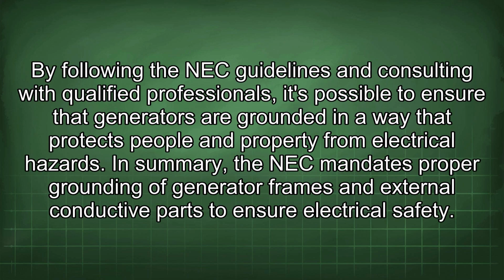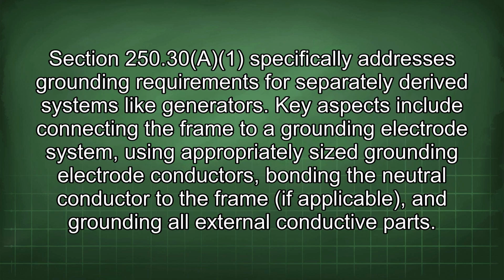By following the NEC guidelines and consulting with qualified professionals, it's possible to ensure the generators are grounded in a way that protects people and property from electrical hazards. In summary, the NEC mandates proper grounding of generator frames and external conductive parts to ensure electrical safety. Section 250.30(A) specifically addresses grounding requirements for separately derived systems like generators.